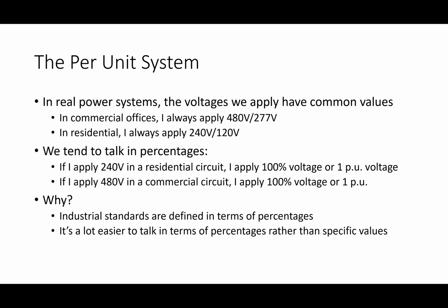Okay. All right. And the way I think about this idea is you're used to, in electronics 1, electronics 2, circuits, whatever, some circuits you're applying 12 volts, sometimes 24 volts, sometimes 5 volts. We don't deal with that in power systems. There's only standard voltages, right? So at every outlet in North America, there's 120 volts. If I'm going to hook up outlets, so these guys here, these lights, they get 277 volts. All right. The motors in this building get 480 volts. All right. There's a standard set of voltages that we use.